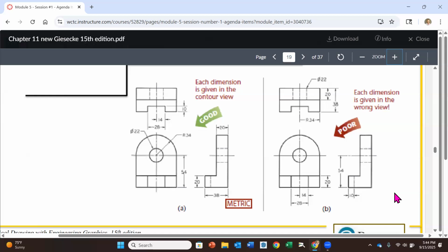Yes. Good example, the 14 for the center line is on there. That's acceptable, even though it's technically not to the hidden line. I would interpret this as a center plane that is down the part. And so that's like the center plane, if you would, of that cutout. So that one I believe is okay. I'm interpreting that as a center plane extension off of that center line, which happens to also be in the middle of the part. Yeah, good question.